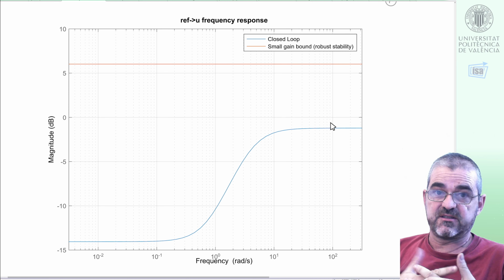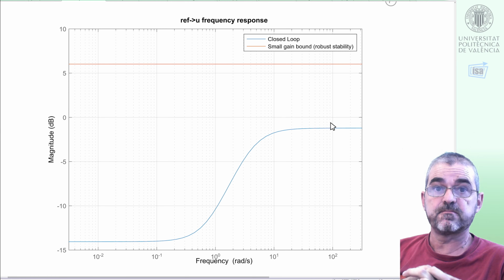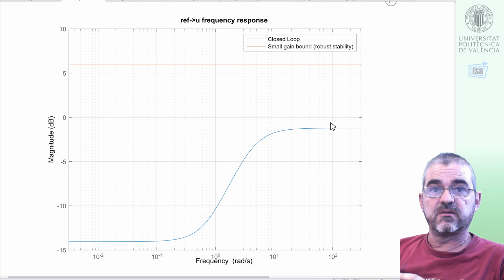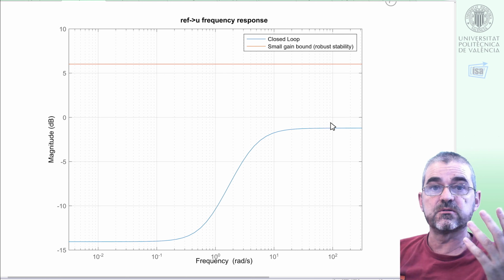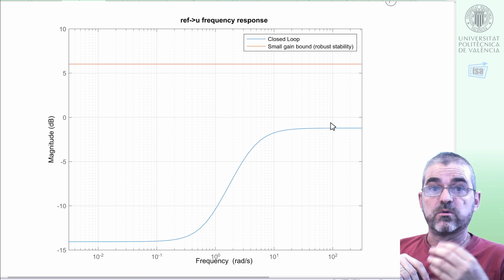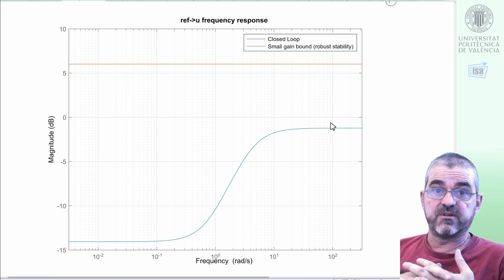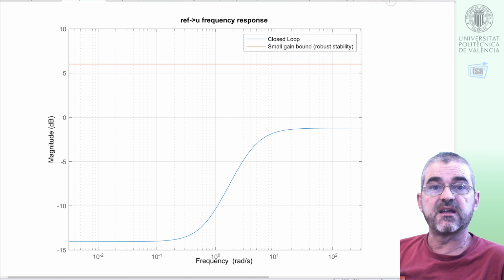So this is it. We concluded here. In this video, we analyzed a mu-synthesis controller result, and when the controller was in arbitrary state space, it had a high order, so we reduced it to order 2, and we also tuned a PID, obtaining basically coincident results.